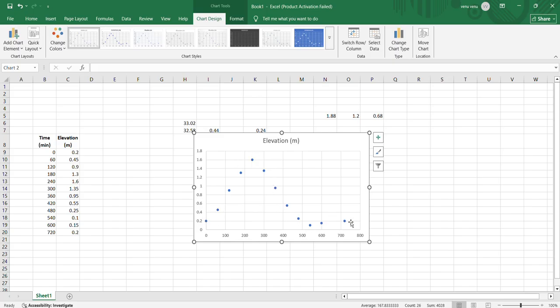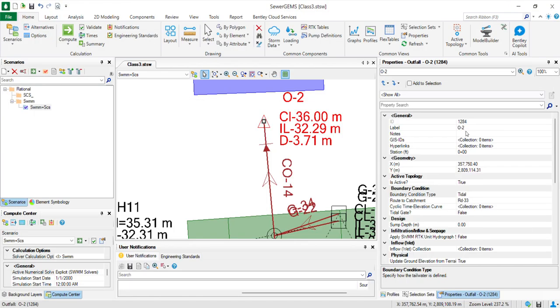We need to add it in the boundary condition to ensure that there will be no backflow effect and no flooding also. Whenever the wave reduces, some amount of water will be discharged from our network to the sea. Then whenever the flow discharge increases, there will be no water in this place; it will be stopped. So in that time we need to use that tidal.